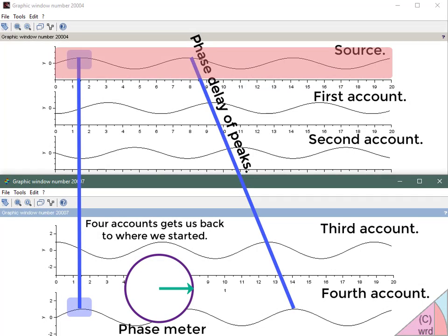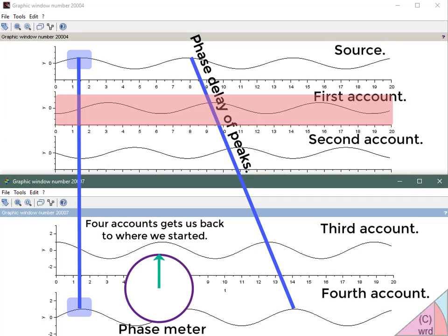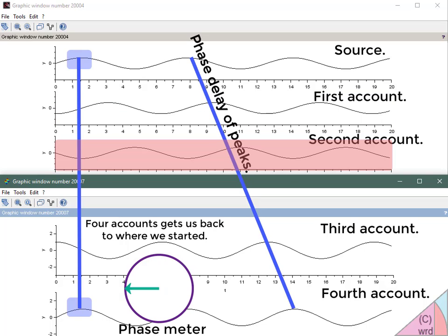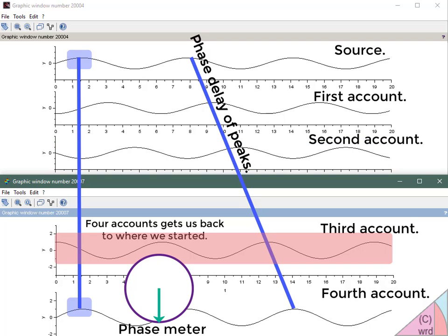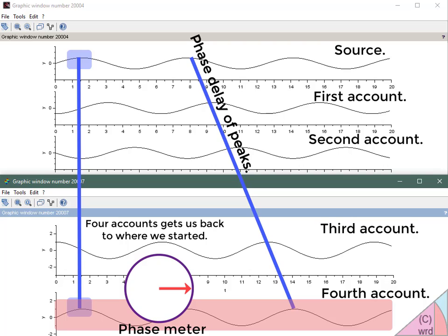Vectors provide an easy shorthand for talking about sine wave phase and signal size. A vector's angle corresponds to a sine wave's degree of delay with respect to another sine wave. Here we highlight a delay sequence from episode 13, showing the corresponding vector representations of each delay. A vector's length represents sine wave amplitude with respect to some original amplitude standard.